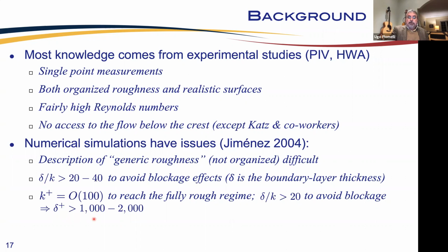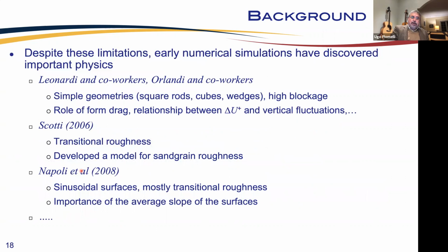The fact that the Reynolds number has to be large enough and the roughness height must be small enough. Now, despite these limitations, there have been a number of very useful studies in the early 2000s. For example, there's been the work by Leonardi and co-workers and Orlandi and co-workers who used simple geometries and high blockage ratio and low Reynolds number.